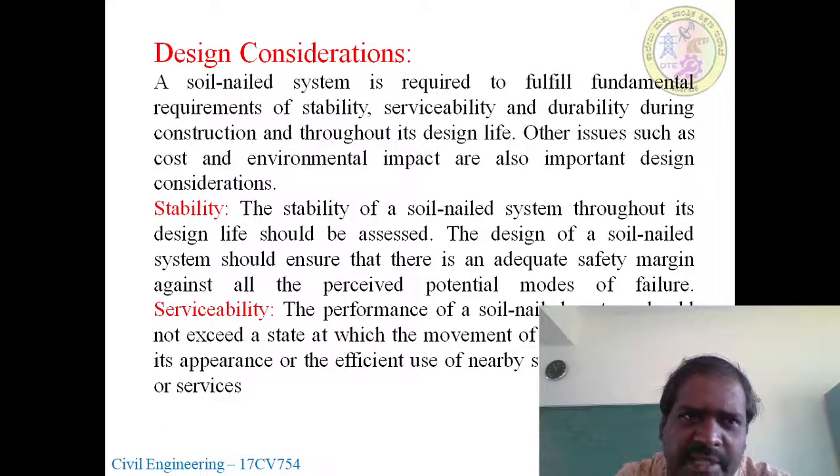And for the design considerations, in the previous session we have studied the geometrical as well as physical and mechanical properties. Next, what considerations must be taken before designing a soil nail system: it is required to fulfill the fundamental requirements of stability, serviceability and durability during the construction and throughout its design life. So here we are talking about the stability, where the structure will be stable, and serviceability, so it will have a long life and a good service will be given, and durability.